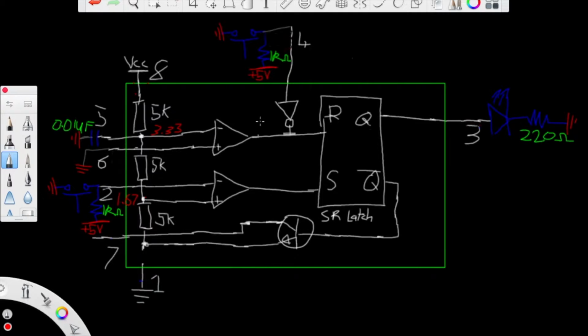And so like always, before I start explaining how it works, I'm just going to run through what's hooked up to the 555 timer. On pin 2 I have a 1 kilo ohm resistor connected to 5 volts, so it's normally pulled up, and then I have a button connected to ground at the input, and the output is connected to pin 2. At pin 4 I have the exact same setup.